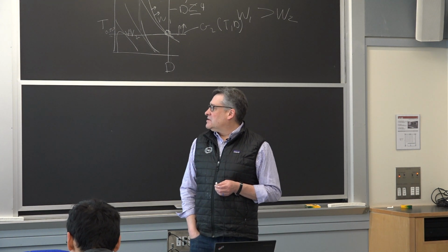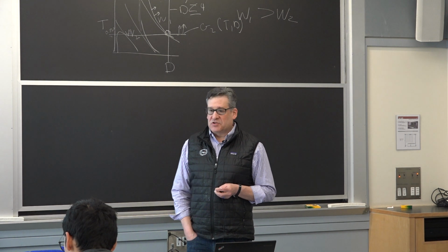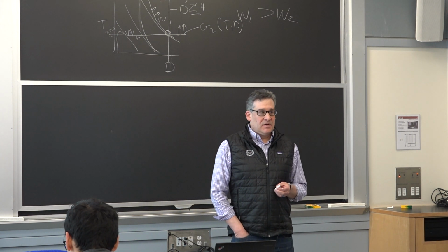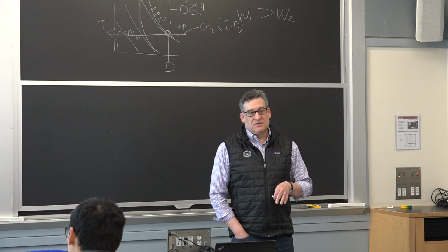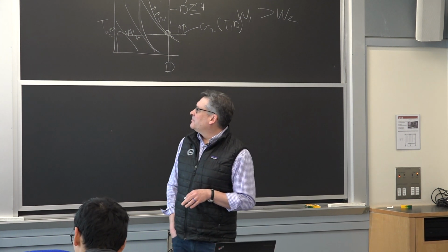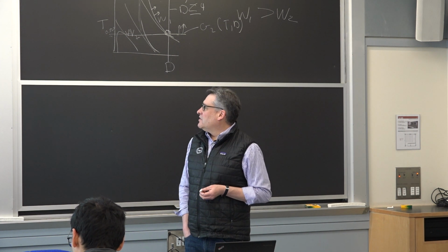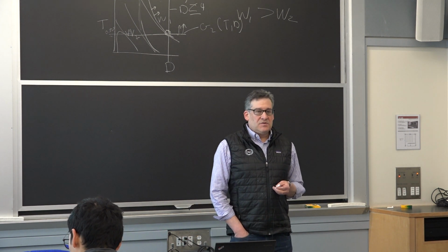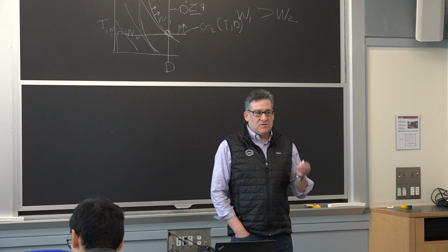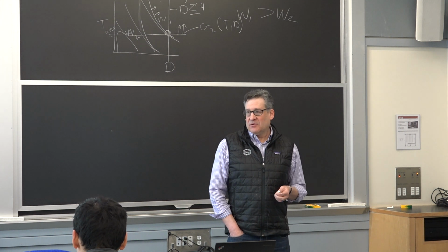Then we're going to define more constraints, which really are a function of the first constraint, H1, H2, H3. And these are the maximum allowable stress minus the actual stress in that member, the stress i comma j, where i is the member, and j is the loading case. So i is the member, A1, A2, A3, one of those bars, and then j is the loading case, P1 or P2. And we've purposely designed these constraints, H1, H2, and H3, so that if we meet those constraints, we won't go beyond the stress level that we have said is the maximum stress we're going to allow in these rods.